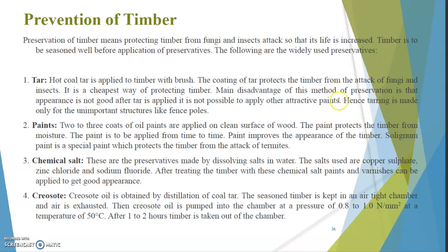So preservation of timber means protecting the timber from fungi and insect attack, so that its lifetime is increased, so that we can make them more durable. Timber is to be seasoned well before the application of preservatives. What they are telling is that preservative application should be done only after the seasoning process. Before the seasoning process, we should not do any external coating to the timber surface. So that is the only condition.